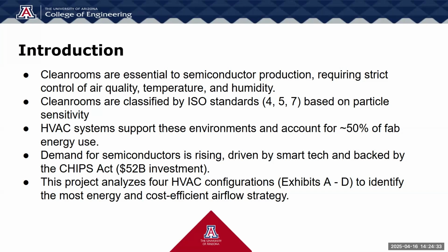that take place require strict control when it comes to particulate matter, temperature, and relative humidity. This is really because semiconductors are very sensitive to contamination, and even a single particle could potentially cause quality issues with the device. So these clean rooms are classified by international standards, and they define the allowable number of particles in the clean room and the required number of air changes per hour. An air change occurs when the volume of the air in the clean room is entirely replaced. So more air changes allows for better contamination control.